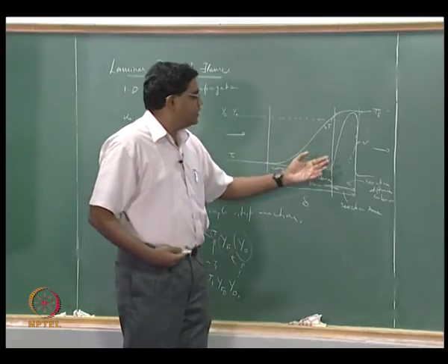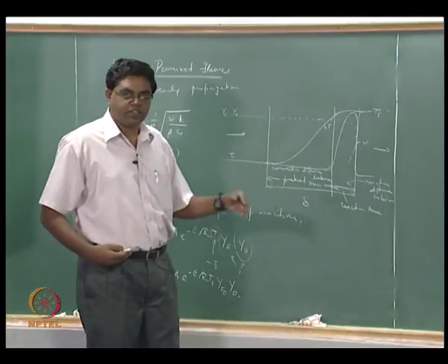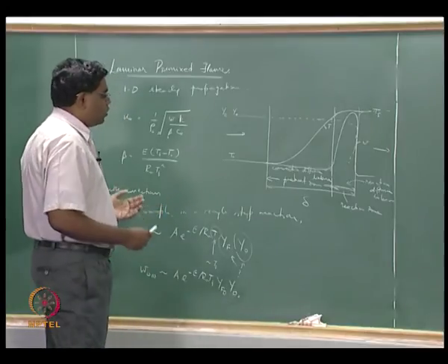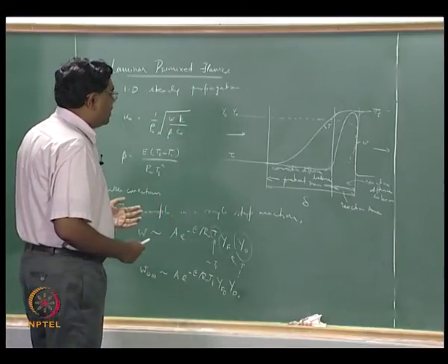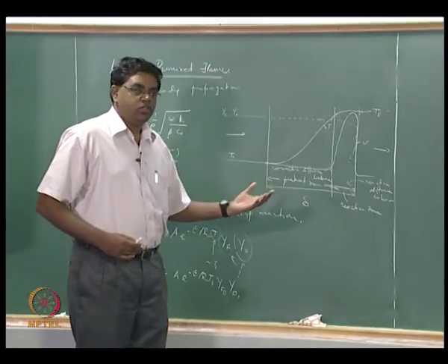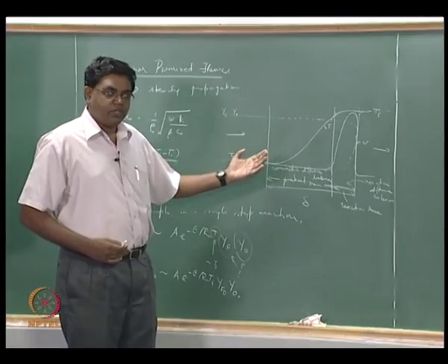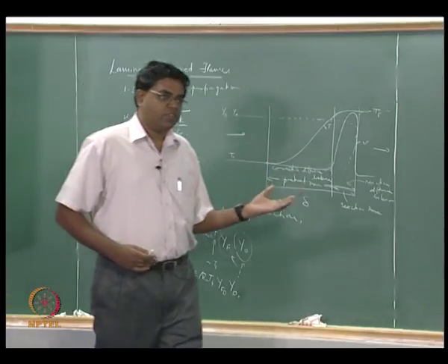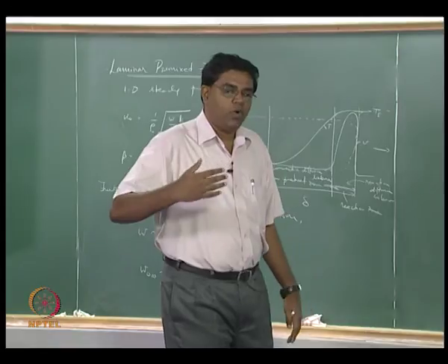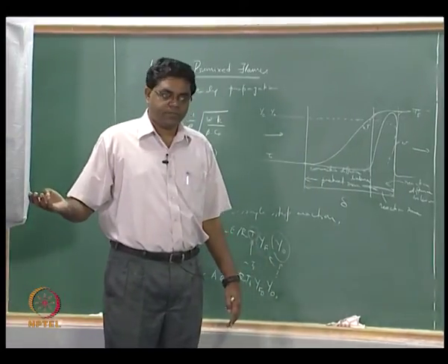Exactly the same thing is happening for product mass, right. So this convective diffusive balance is happening for the product species mass as well, and if you were to now invoke a unity Lewis number for the products, right. So the Lewis number is the one that is trying to tell you how well a species can diffuse versus how well it can conduct heat, right.